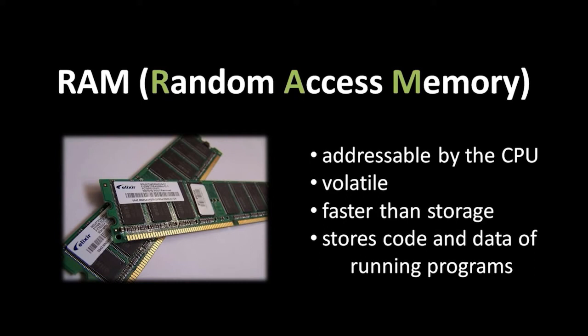address. A notable characteristic of RAM is that it's volatile, meaning that as soon as a RAM chip loses its steady stream of power, the content of the RAM gets scrambled. None of the bits can be relied upon anymore because, without power, they get flipped unpredictably. What this means in practice is that when you turn off your computer, the contents of RAM are lost nearly instantly. The next time the computer is turned on, the contents of memory start off in a total jumble, as a bunch of random garbage.